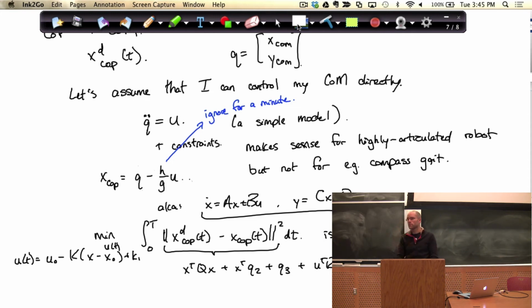Yeah. So we don't have any guarantees yet that the trajectory for the center of mass is feasible, only by being conservative about our choice of the ZMP. If you want to solve a slightly harder problem, then you can add these constraints in and then solve a convex optimization to solve this problem. Right? You can do linear model predictive control. You could solve a big quadratic program to come up with the trajectory, and maybe you have to do it at every time step to get a feedback controller out. You can be accurate with that, right?